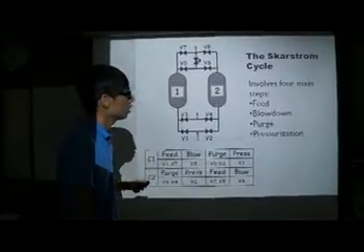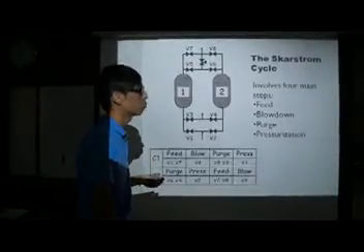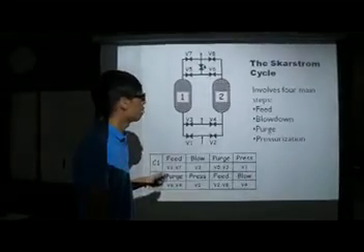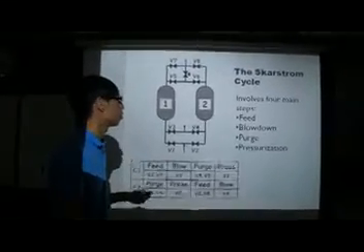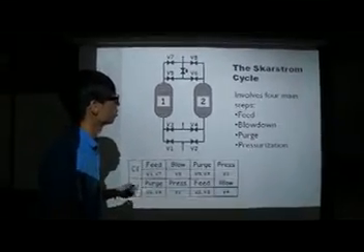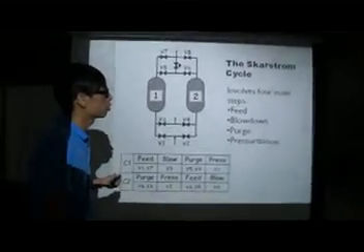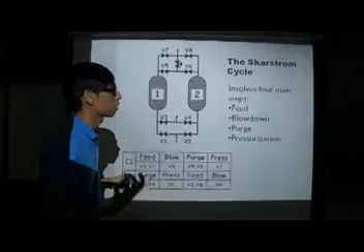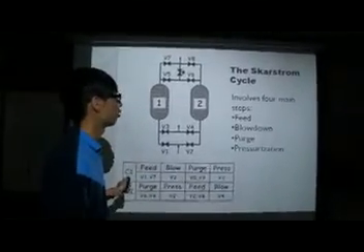We need the purge step because the blowdown step is not sufficient to entirely remove all the adsorbed components. In a purge step, you introduce a purge stream into the adsorption column so that the purge stream carries the adsorbed components out together with it.